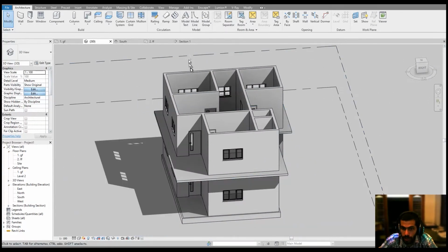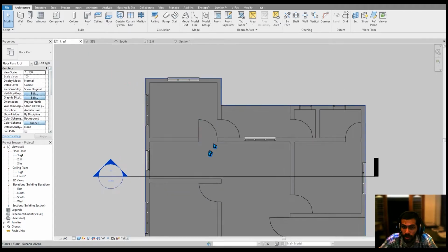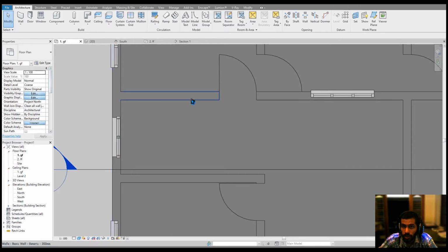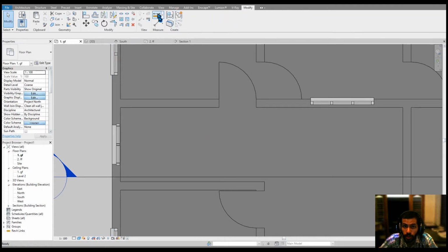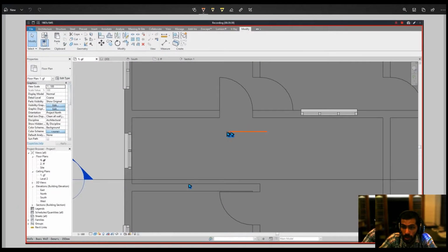Alright, now let's try to place a stair right here. So let's maybe create Dual Leg Stair. So first, before drawing that, I'd like to understand the width of the stair. That is probably 180. So the stair will go right through this side, and I'll have a landing right here, and it will come up to this side.